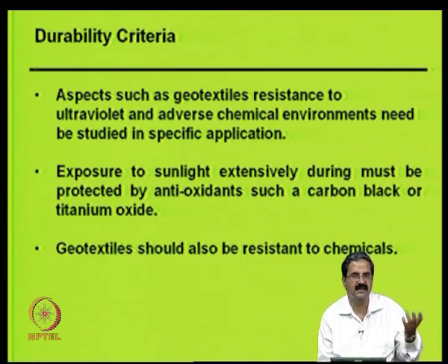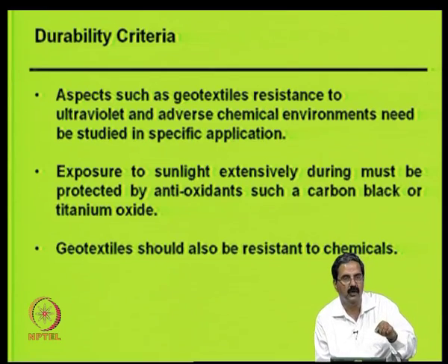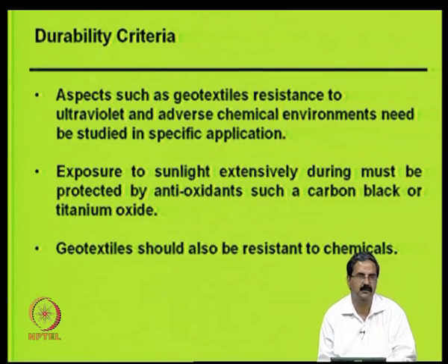In a conventional geotextile design, what are you doing? You have only 2 criteria: one is soil suspension criteria, the other one is permeability criteria, using those D60, D10 sizes, that is all. There is no other design method, but Giroud looked into it in more detail, looked at all these factors, and came out with a design method which is quite reasonably well established.